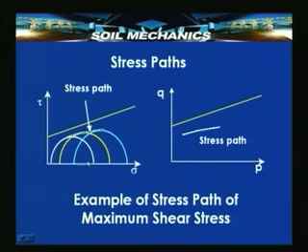Then as the loading has changed during the test with every Mohr circle, the position of the maximum shear stress point has changed from here to here to here. And in a p-q graph, we can see the same path through which maximum shear stress has changed with loading. It is this that is known as the stress path. This stress path is for maximum shear stress and how it varies with loading. Now, here no failure is involved at the moment.